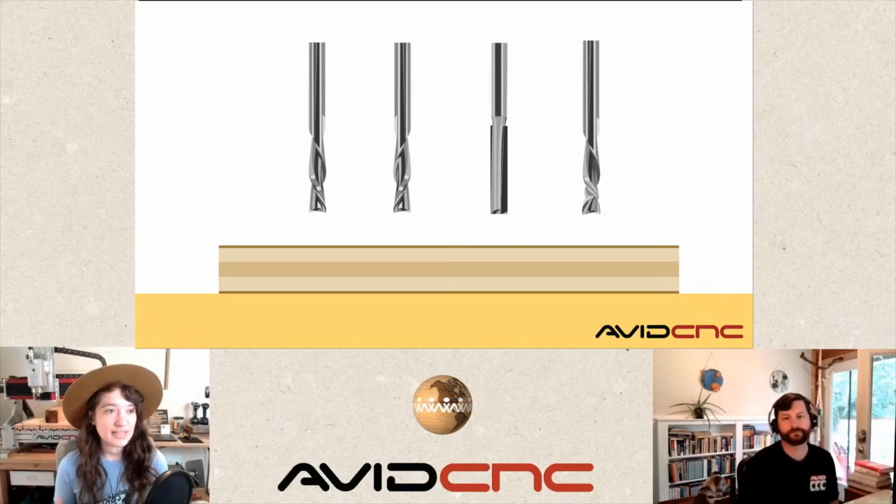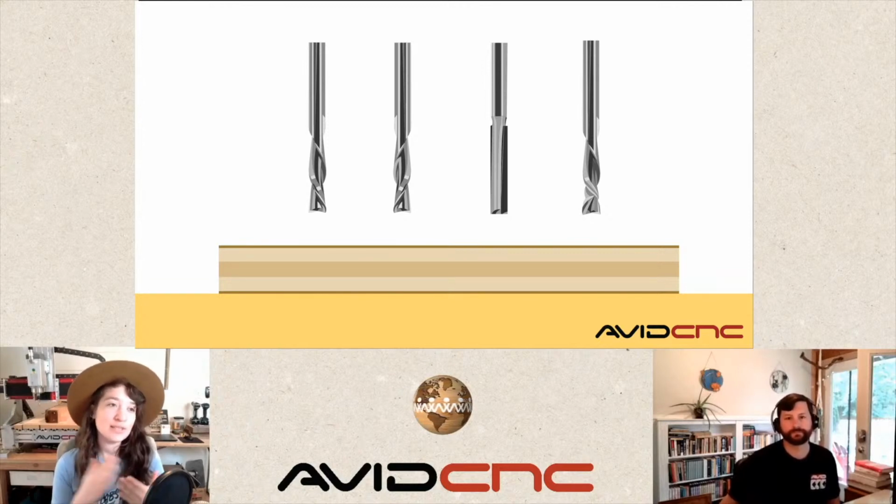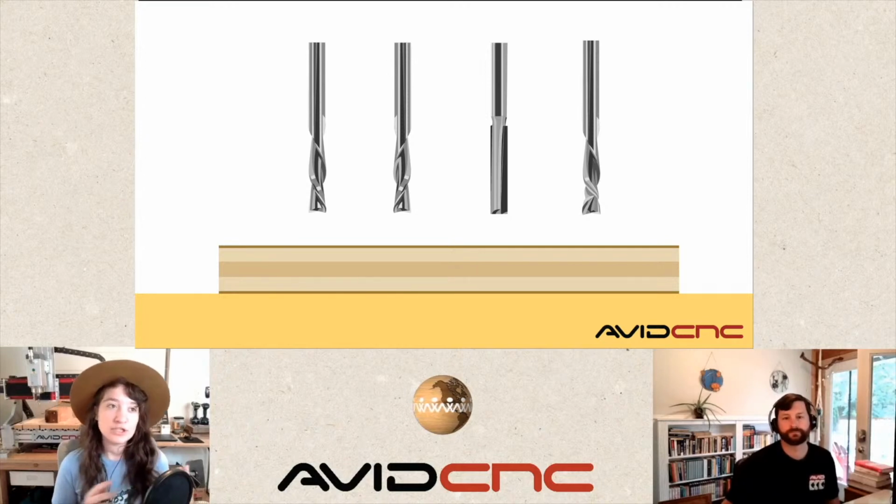The things you're going to think about first is your diameter. Is there a probability of deflection or chatter depending on the diameter of your tool? What is the flute count, and does this affect your RPM range or your achievable feed rates? And then the flute type. This is definitely going to be very important in regards to the material you have. So we have a spiral bit, which has different geometries to consider: your up, your down, and compression bit. And then you also have your straight bit, which is a great neutral and more cost-effective choice.